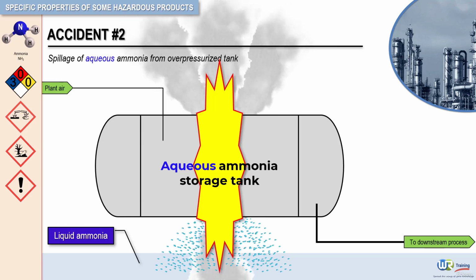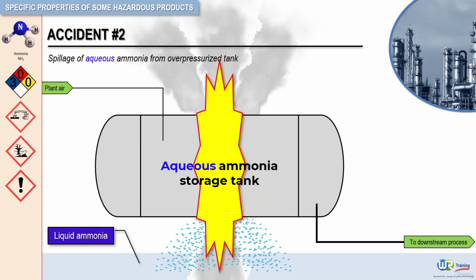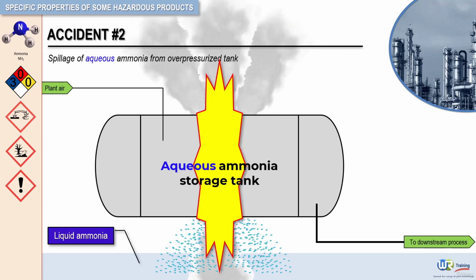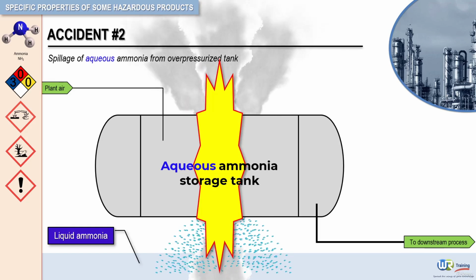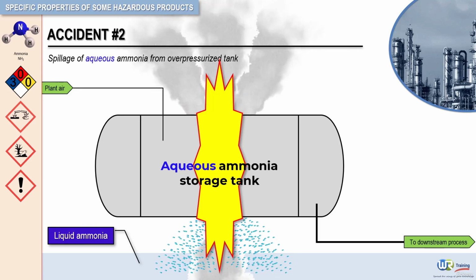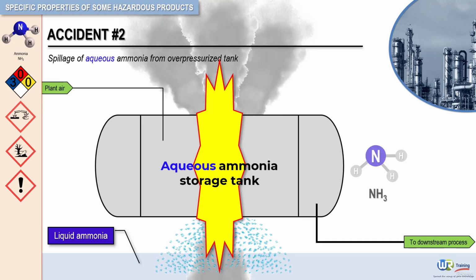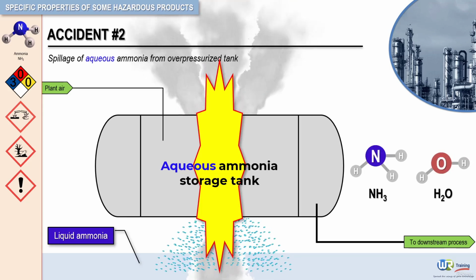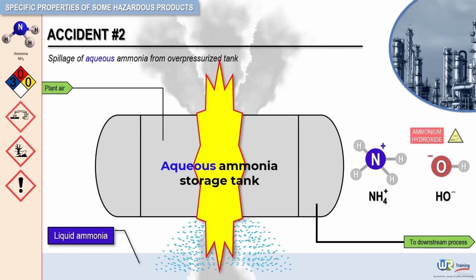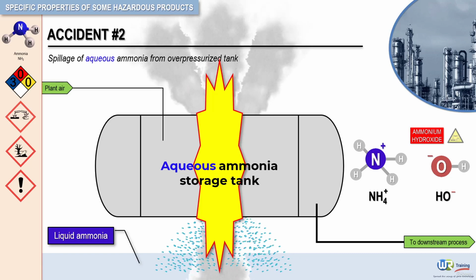Now, the use of water sprays in tackling aqueous solutions of ammonia was correct here, but keep in mind extra care must be taken in the application of water to anhydrous ammonia. The heat of reaction between water and anhydrous ammonia can lead to a more rapid vaporization of the ammonia. In addition, recall, when anhydrous ammonia contacts water or any type of moisture, it quickly combines with water to form ammonium hydroxide, which is a very caustic solution that can cause irritation and burns to human tissues.